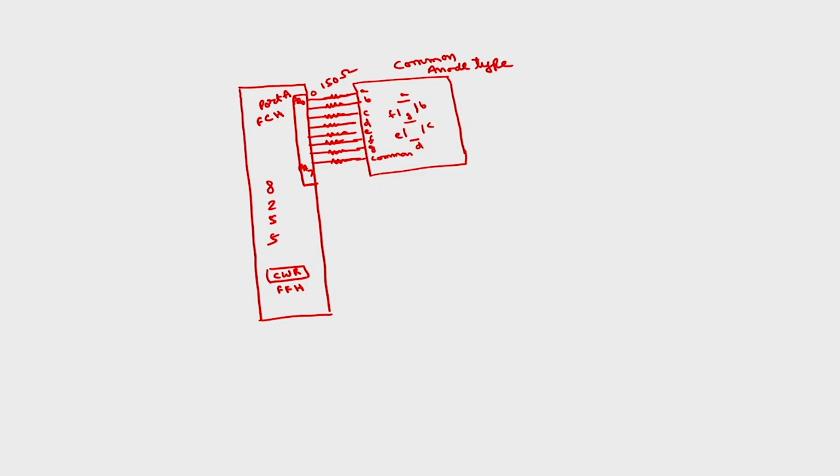This is interfacing. So if I want to implement a decimal counter on this particular 7 segment display, it means first you display 0, then 1, then 2, and so on up to 9, then after 9 again you come back to 0 continuously, and you allow some time between 2 consecutive counts, say 1 millisecond or 1 microsecond, that depends upon the application.